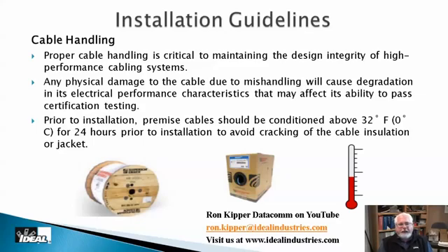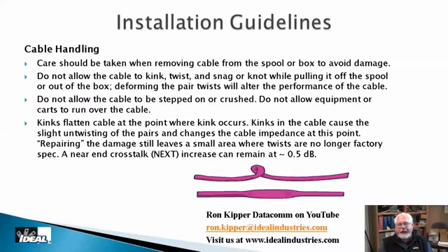And as far as handling the cable, make sure that when you pull the cable off the spool right out of the box, it's not getting kinked as it comes out, because in many cases you're pulling multiple runs of cable at one time, not just one cable at a time. And make sure when you're pulling around corners, you're using those pulleys and other things so we do not damage the cable during the process. And don't let it get stepped on or crushed in the pulling station as well.